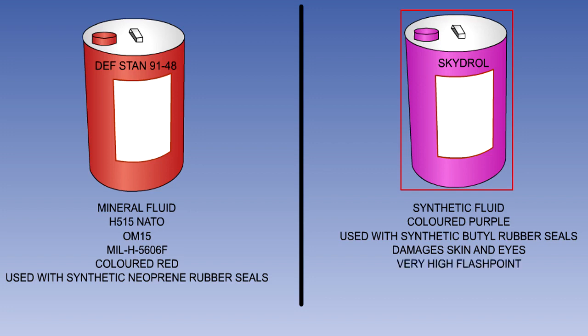It has a very high flash point of 170 degrees centigrade and is less prone to cavitation than mineral oil type fluid because of its high boiling point. Skydrol is the most dangerous to personnel, but most modern airliners use Skydrol in their hydraulic systems.